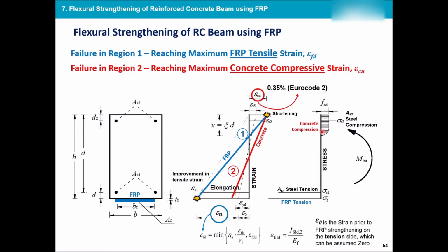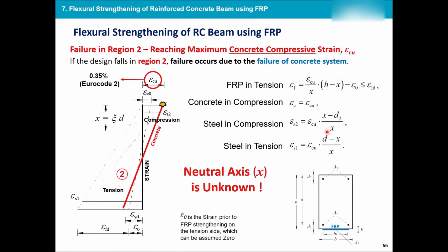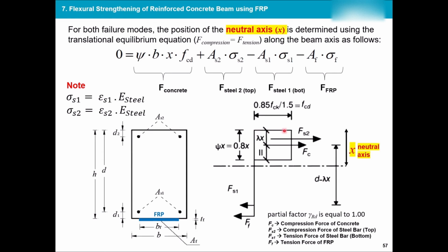This area, we just simplified it, so we are representing it with a square or a rectangle. So I have the area of this. I know how much is this, how much is this. And then I just multiply it by the strength, which is the maximum stress of my concrete. Isn't this the design concrete strength?